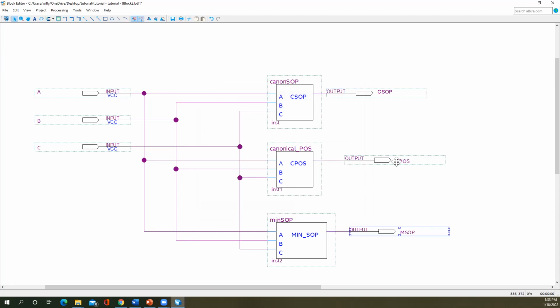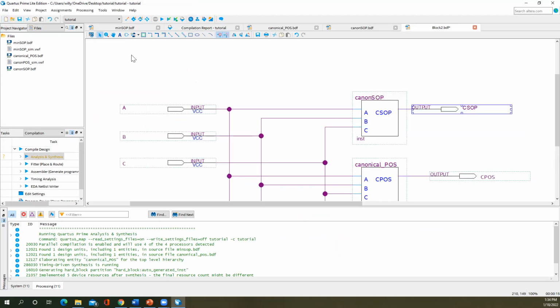All right. And it's okay that I use the same names that we use in these blocks. These names are internal to this module. These names belong to this particular module schematic. We can use them again because they're in a different schematic. Same way with A, B, and C. I can use these names again because I'm only using them once in the schematic. Anything that's inside this block is internal to the circuit. So even though we use the same names, there won't be a naming conflict. Like I could have called this X, Y, and Z, but I still could have connected X to all the A's and so forth. All right. If I want to touch that again, I can do that.